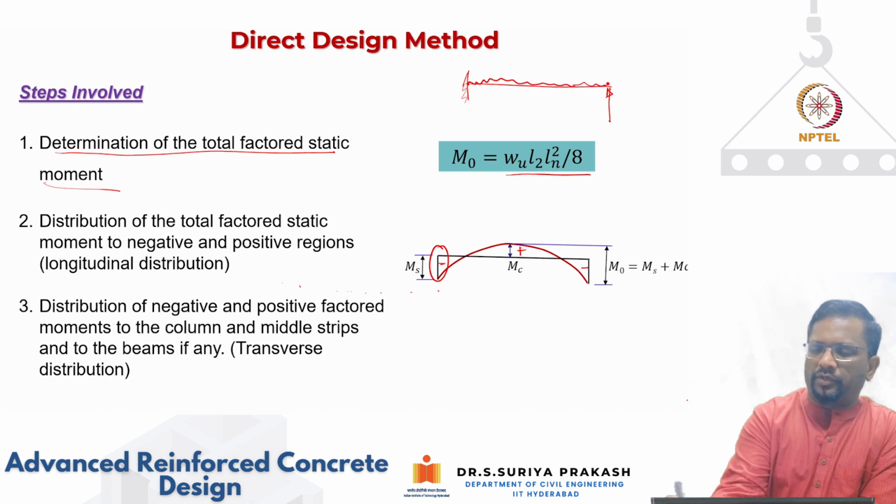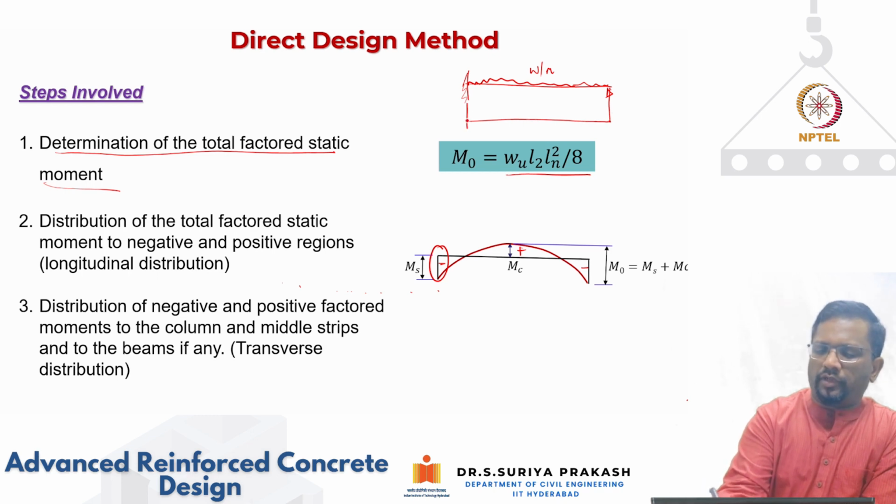Let's say it is subjected to w per meter. Now, what would be the bending moment diagram? Okay, you're going to have negative moment here and 0 moment here. So it's going to go like this and come like this.